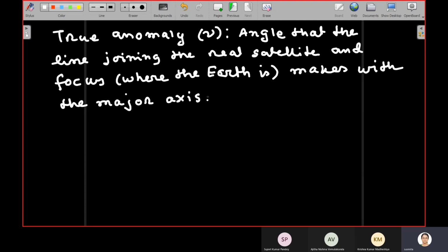Okay, actually we are interested in finding the true anomaly, but in the orbital parameters we are given mean anomaly. And yesterday I noted that the orbital parameters or Keplerian parameters are given at a particular time called time of ephemeris, and the broadcast parameters are valid for 2 hours. So every 2 hours, in case of GPS and IRNSS, they are changed by the satellite. So all the sets are uploaded by the control segment and then they are broadcast by the satellites. The satellites change the parameters every 2 hours.